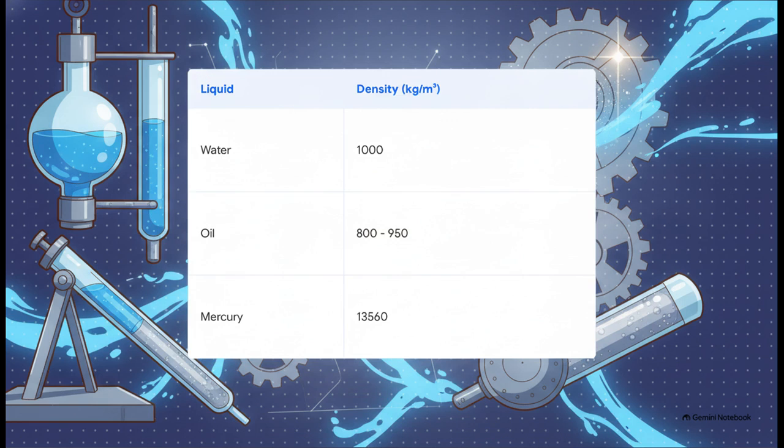We can do this using a basic U-tube, a well type for easier single-column reading, or an inclined manometer for maximum sensitivity at low pressures. And the fluid you choose changes everything. Water has a density of 1,000 kilograms per cubic meter. Mercury, on the other hand, is over 13 times denser.